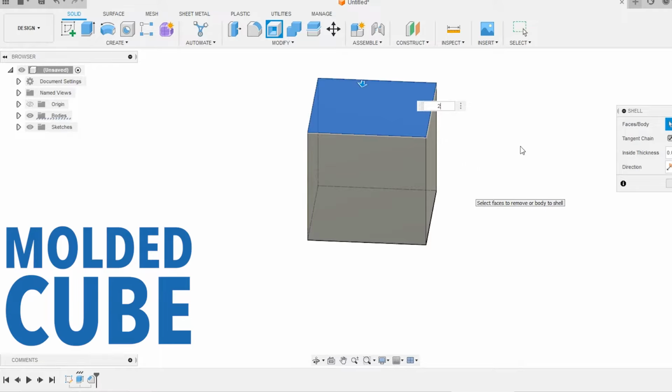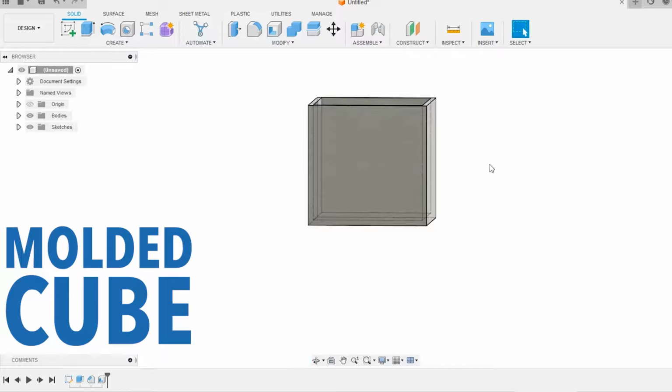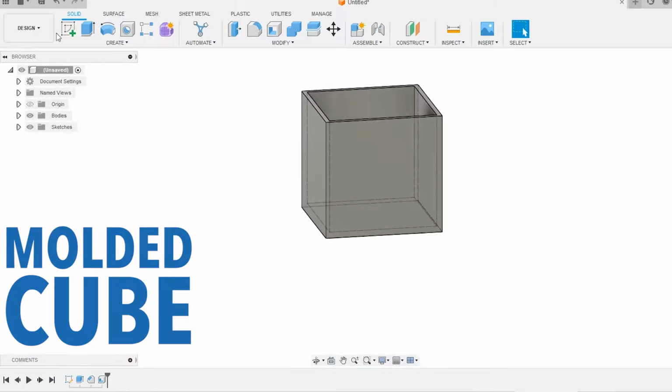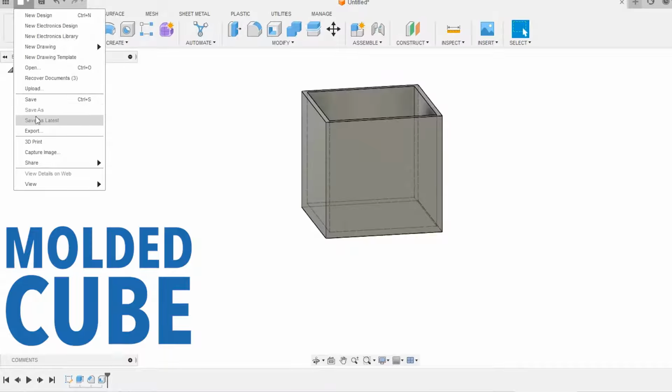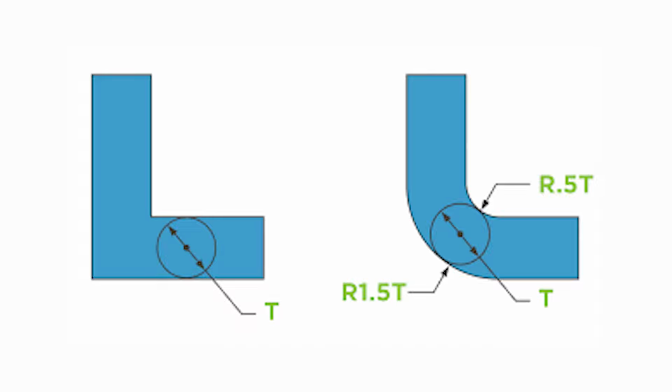After that, you cannot have a solid brick or a large mass of plastic anywhere inside an injection mold. Otherwise, it'll shrink and cause all sorts of problems with the final part. So you actually have to remove the entire center of the cube, removing an entire face so that a cavity can be made. We made the thin walls 2 millimeters thick to have a nice rigid functional part, because this cube is going to be used as an end cap for a fence post or something like that. Now the cube is no longer a cube, it's more like a dish with one wall missing and thin walls throughout, but it is injection moldable now. And then of course you want to fillet every single sharp edge, because sharp edges do not exist in the real world.